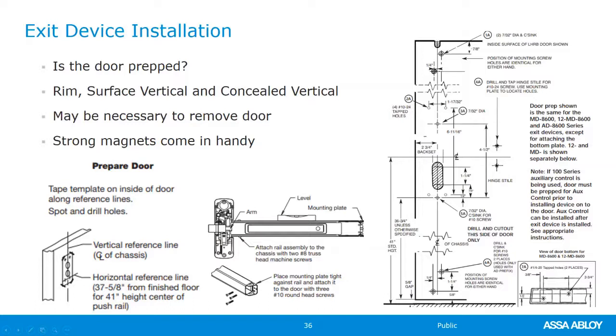It's important to take the time, and sometimes it takes way more time to measure and get everything put on the door than it actually does for the install itself. But what that ensures is that we only have to install it one time. We don't have to waller out or enlarge any of our installation holes because we missed the measurement the first time, which will cut down on installation time. It'll also cut down on recall trips or second trips out to work on something.